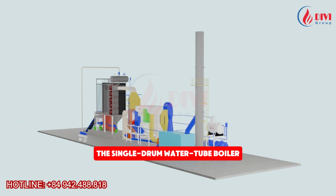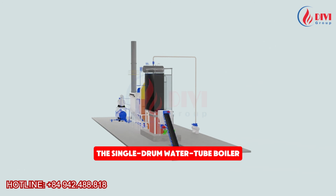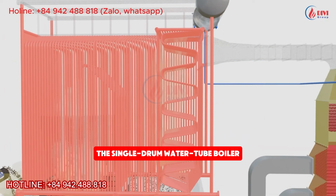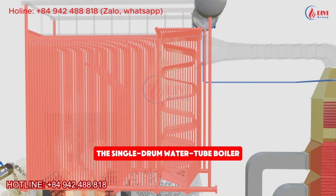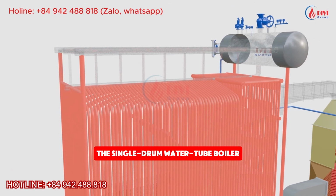Finally, the single-drum water tube boiler. Like the previous design, the furnace is enclosed by water tubes that absorb radiant heat and generate steam. The convective heat transfer section is also built entirely with water tubes. However, this design uses only one upper drum, which contains both water and steam.